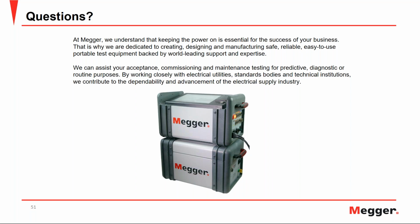That's a very good question, I would say, because this question is coming from someone who has been out in the field and has run into these kinds of situations. So as we know, many times we don't have access to standard outlet power, and in those cases you would use a generator to give the power to the unit. It is very important that whenever you use a generator, you make sure that generator is also tied to the same grounding point to which your test set and the test asset is going to be grounded.